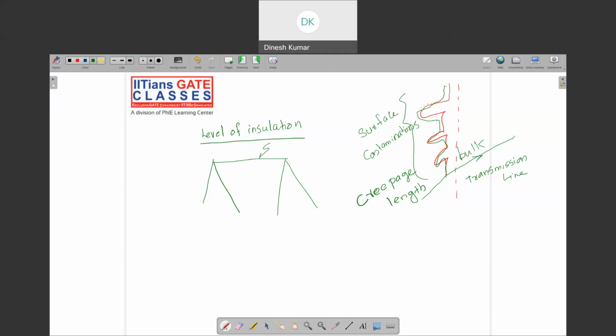If you look at the tower, there is a wire on the top of the tower that is grounded, connected to the tower. This is for lightning protection, because a lightning strike will happen on the highest line, which is the line above the tower.